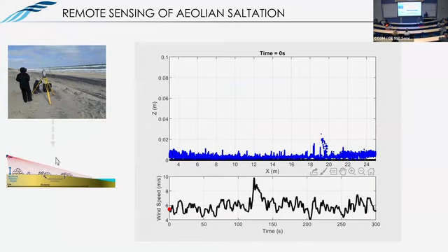So this is over 20 meters of a beach. I'm going to play a video in a second, and this is a really short clip, just 5 minutes, to give some insights in terms of what we can see. You'll see we're hovering right around the threshold velocity for wind-driven sediment transport. So really anything above 5.5, 6 meters per second, you might get some sediment transport.